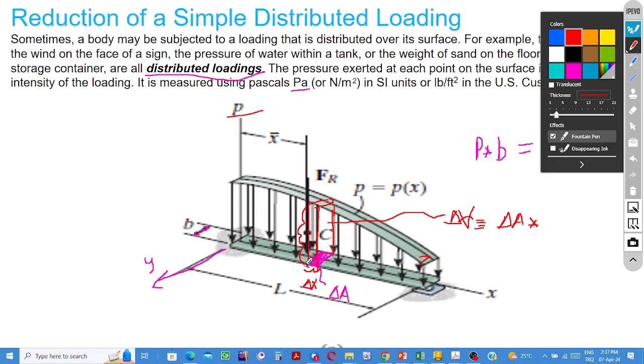But this prism is special. In this direction, the unit is not distance, it is pressure, because the rectangular prism extends from the contact surface to the load diagram. So the height of the prism is P. Here in this region it is equal to that much. It is the volume. This part of the load is equal to the volume of this rectangular prism.